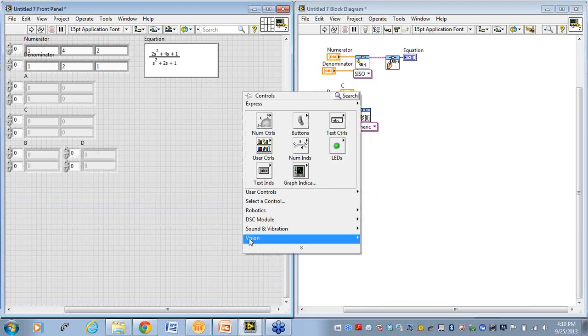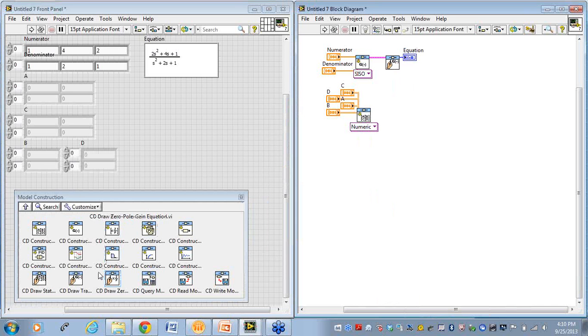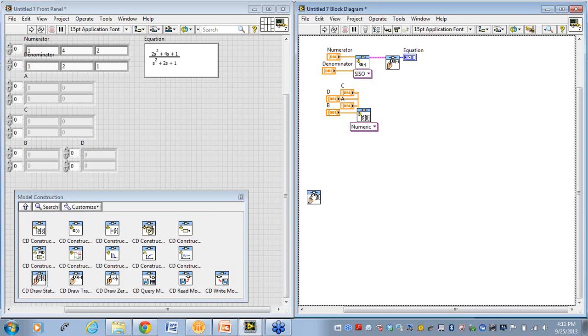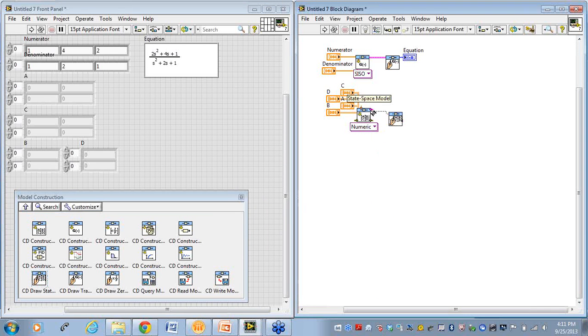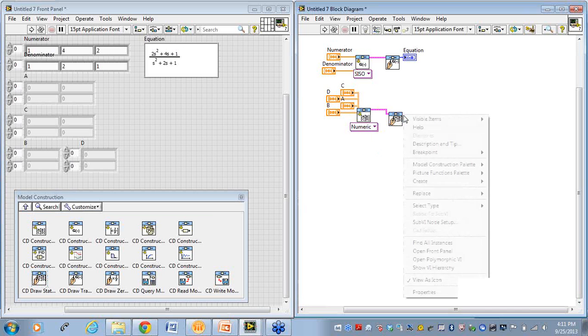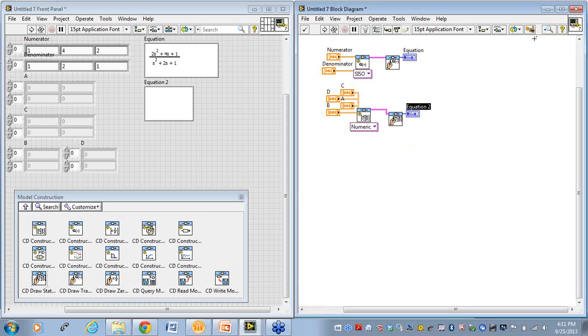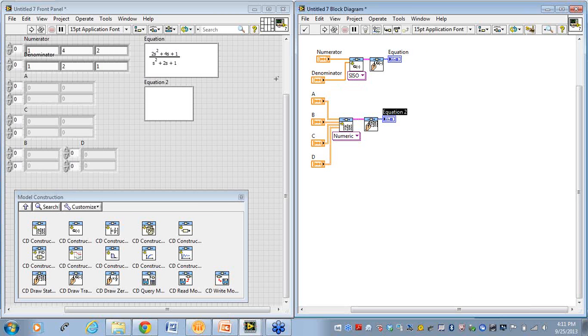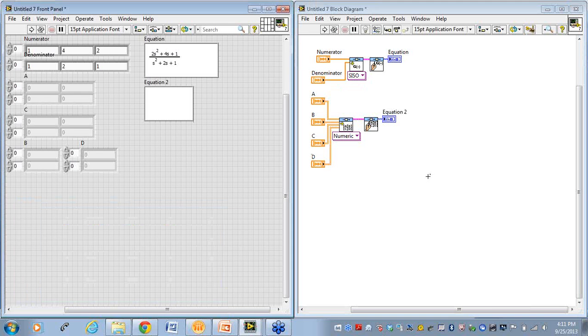And again I need to draw this transfer function in order for me to be able to show it on the front panel. So I'm going to use this VI here, connect it, and add a simple indicator here. Now once I fill in the values for my 4 matrices, my state equations will come up here. But before that, I want to show you another speciality, which is using the MathScript node to convert representations as well as to obtain the transfer function.